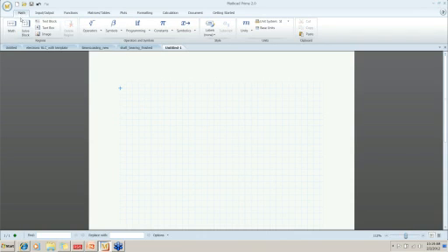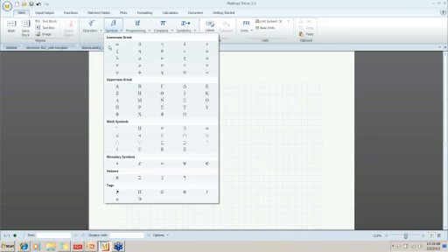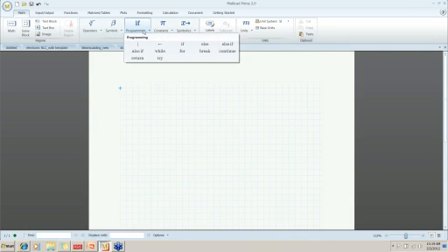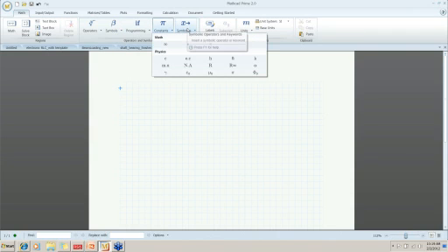Going back to the math tab here, these are the operators. Here are the Greek characters, so we have full access to all of the Greek characters there. Here are the programming constructs, to write Mathcad inline programs, which are analogous to macros in Excel. Built-in constants, the Symbolics button. So these are some of the things that are on the math ribbon.